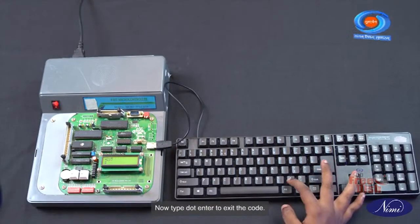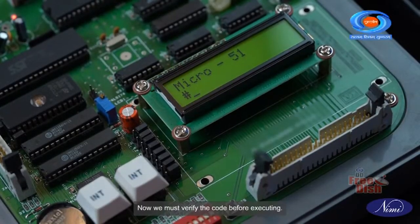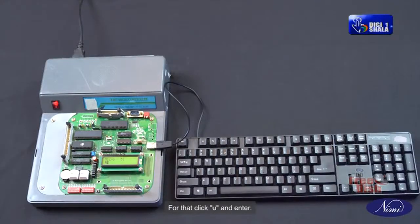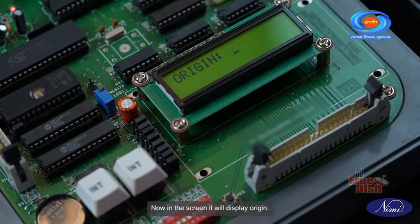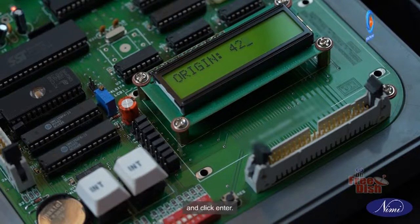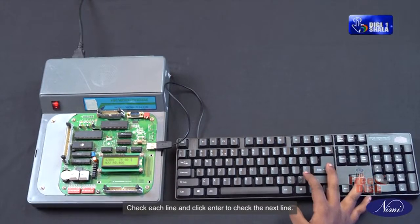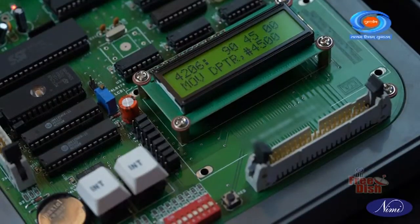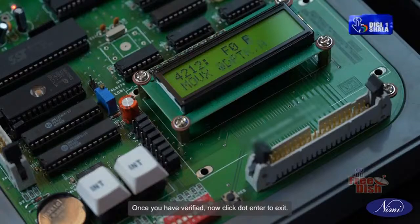Now type .enter to exit the code. Now we must verify the code before executing. For that, click U and enter. Now on the screen it will display origin. Give the starting address of the code, that is 4200, and click enter. Check each line and click enter to check the next line. Once you have verified, now click .enter to exit.